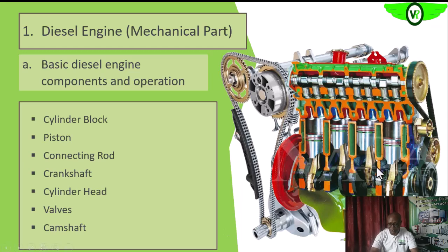So this is a coupled engine now, as we have been discussing. These are the pistons, and this is the combustion chamber. In the power stroke, after combustion, the energy contained in the combustion product will force this piston to move down. So that high kinetic energy is converted to movement of the piston, and the connecting rod will transfer that movement to the crankshaft. This is the crankshaft. It will convert it to rotating mechanical energy that will be available at the flywheel, as you can see here.